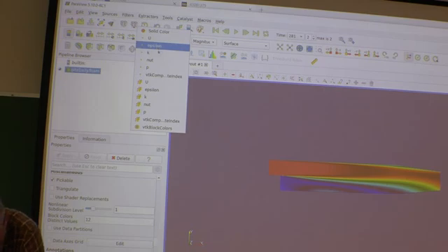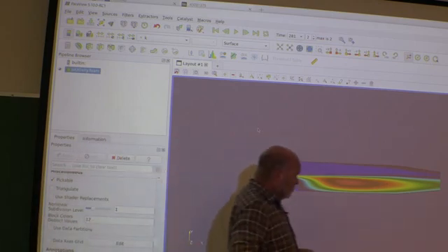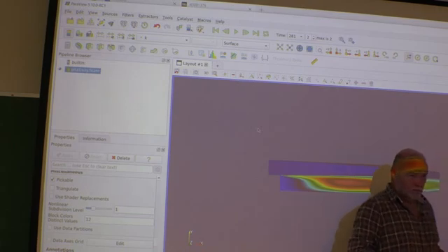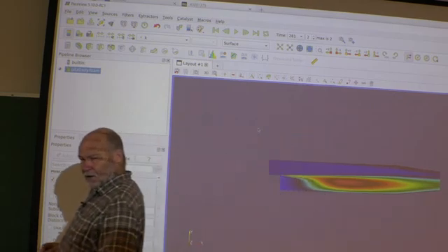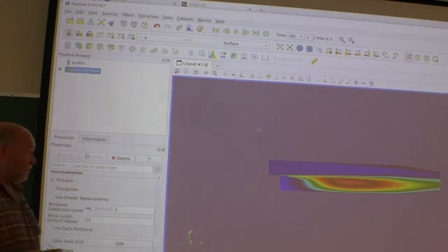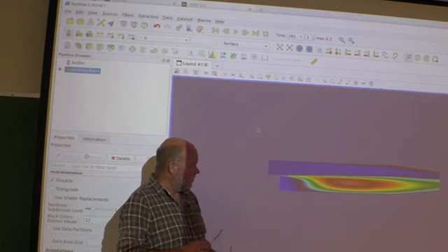So let's start with the turbulent kinetic energy. It looks something like this. And if you look at the numbers here, it's not that big, 5.5. Does that make sense? We are sending in 10 meters per second. That's the bulk velocity coming in at the inlet.